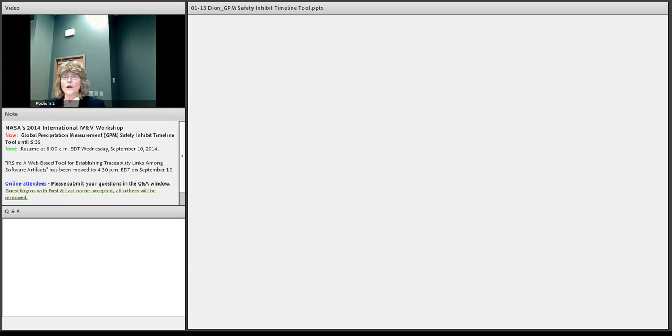Now, something I didn't mention, and I should, for all these X's here, we also have the option of putting them on a prohibited command list. What that does for us is, if we don't want to have a deployment or an opening of a valve or so forth, we can put it on a prohibited command list, and if the GSC sees that that command is initiated, it will not let it go through. Okay, so that's another safety feature you have to have for safety critical software.